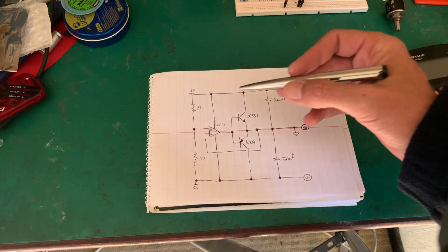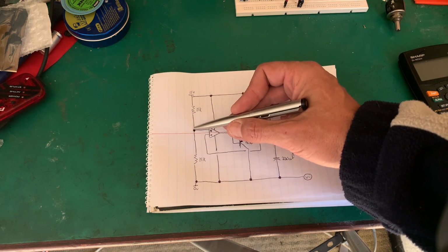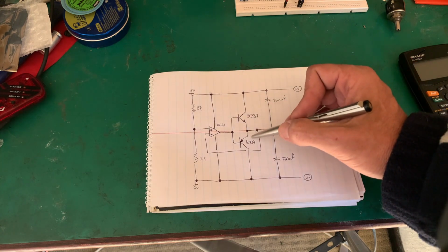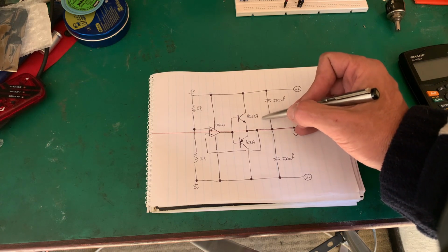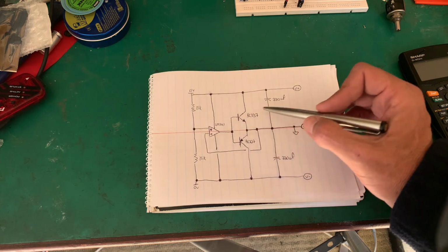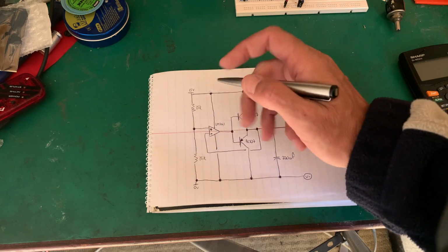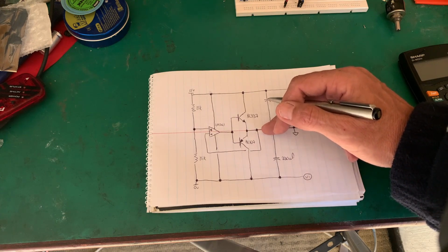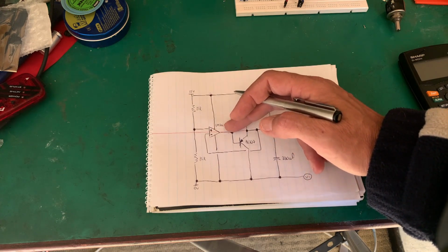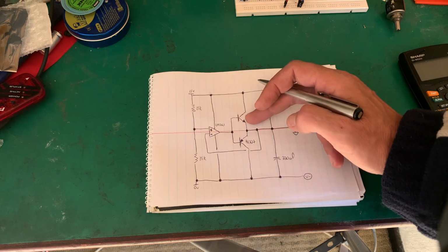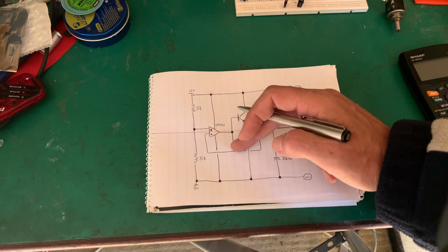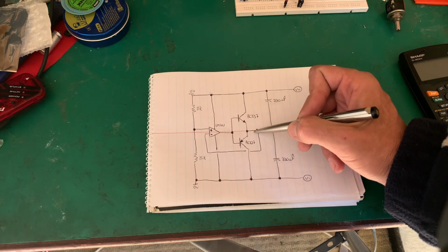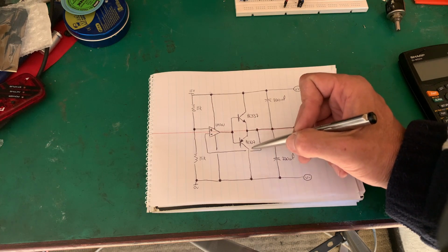Can you see that? We've got a reference of 7.5 and we've got this feedback on that leg there. So we want 7.5 volts here. So what is going to happen? We switch on our power. This goes to 7.5 volts. That is 0 volts. This op-amp is going to switch on that transistor harder. It's going to switch off that transistor. We're going to bring that voltage to here. It starts coming up, it gets to 7.5.